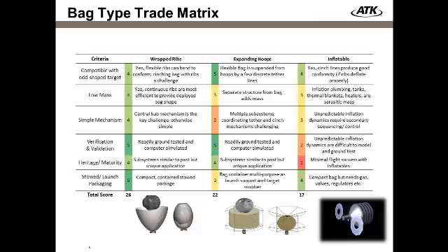The simple mechanization: how do you release this, and is it with a lot of motors, or is it a simple strain energy spring-loaded device that comes out in a synchronized fashion? We've done more of the latter than the prior, again, deploying things out with springs in an articulated manner or driven out with a simple drive motor.